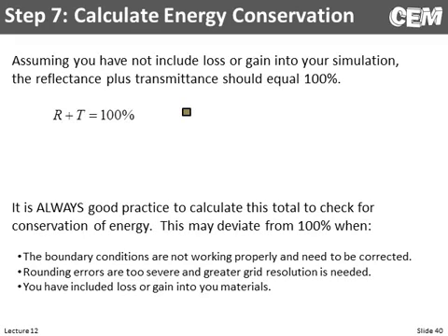And if you do have loss or gain built into your model, I always suggest, okay, build that in, get everything working, but in your final check, turn the loss or gain off for a moment. Run your simulation, make sure you get conservation of energy, and then you have one more level of security that your code really is working.